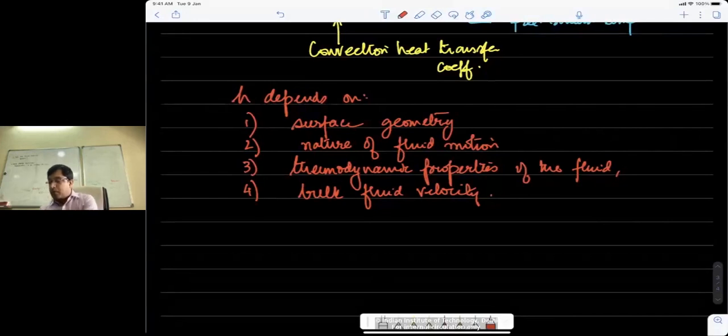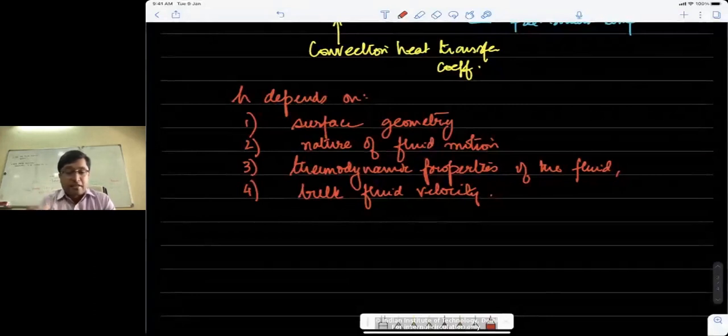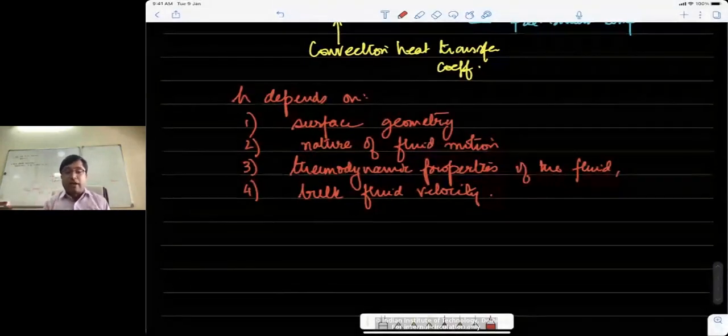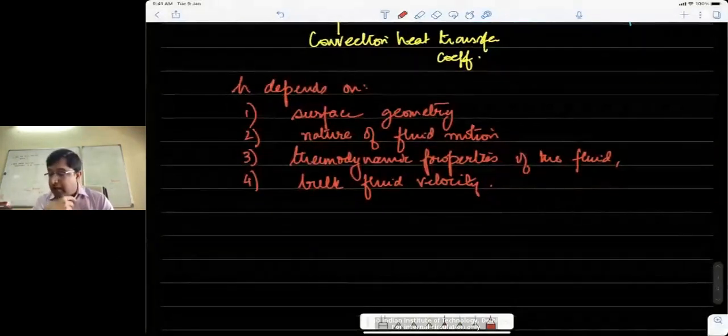Now, though we are not at that stage, when we were growing up there used to be frequent power cuts, and we had this makeshift fan with us in the houses all the time. So using a fan to regulate your body temperature, to cool yourself down, is actually a case of forced convection. But just sitting there and allowing the surrounding air to cool you would be an example of free convection. So please think of it this way: the external means of driving the flow will define whether it's forced or free convection.